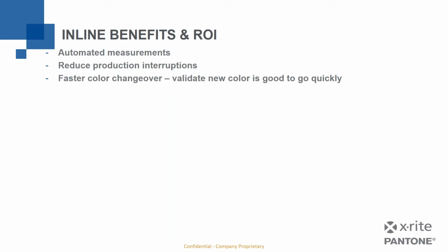It also can help you if you're doing color changeover. So if you're extruding something, could be any of these continuous flow kind of systems, carpet, coil, extruding vinyl siding, extruding vinyl molding or plastics of any kind. You do a color changeover, and the device, since it's measuring inline as you're doing the changeover, can tell you quickly as soon as you've reached, yep, okay, my color is good. I'm producing my first color. The color is good.